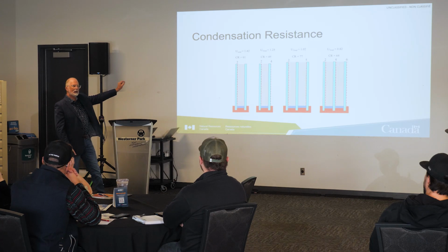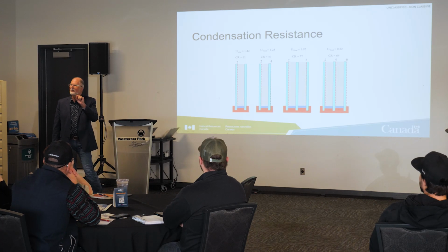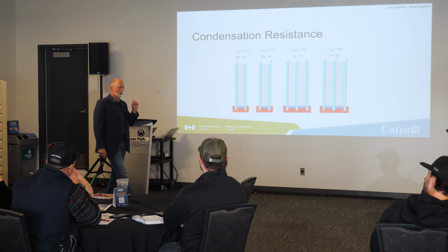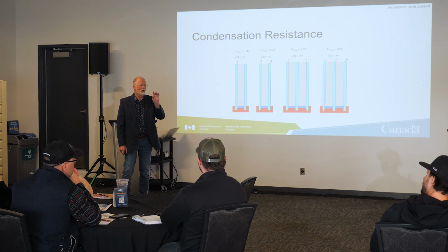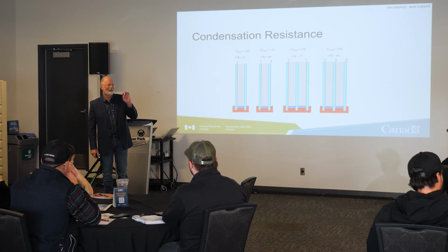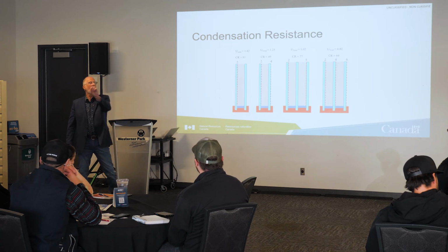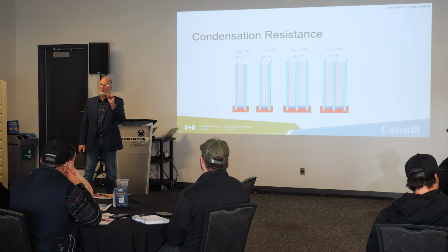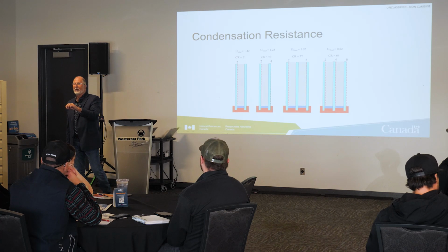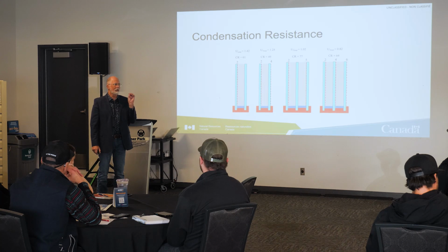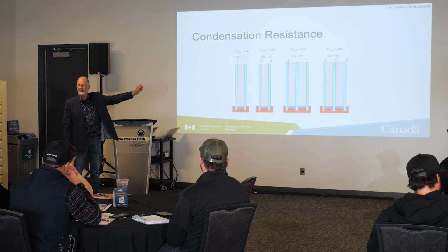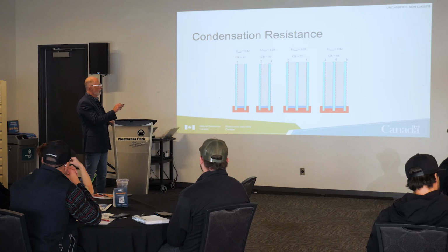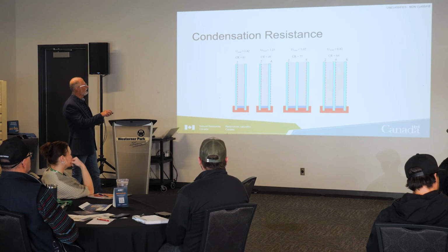So what other criteria have we learned about this morning other than just asking for a 1.1? What's the second most important? Position of the coatings. Position of the coatings, which dictates what? Solar heat gain. So do I want a lot of free heat in the summertime? No. I want to bounce it out in the summertime. Do I want free heat in the wintertime? Absolutely. So now I'm looking at that, and then I'm going, what's the risk of having condensation in this house? And that's dictated by the coatings, not just the overall U value, but the coating.